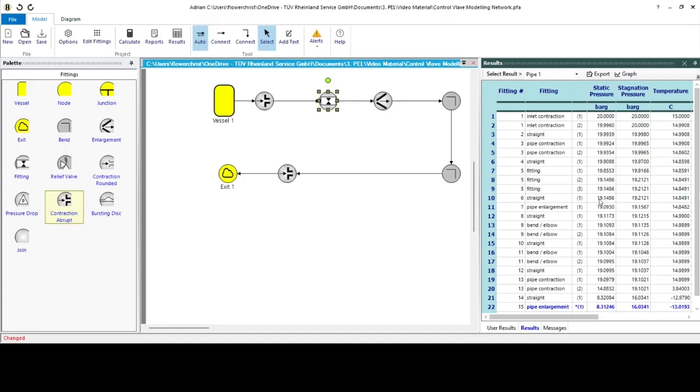So it's a bit of an iterative process. We model the control valves in this choked and non-choked way. We can build the model and run it first as if you might have choked flow, and check whether you've got choked flow. If you haven't, then go back into that little fitting model, make the diameter the same, but put in the K value, and that will predict the pressure loss through it. And hopefully you've got an answer that you need.